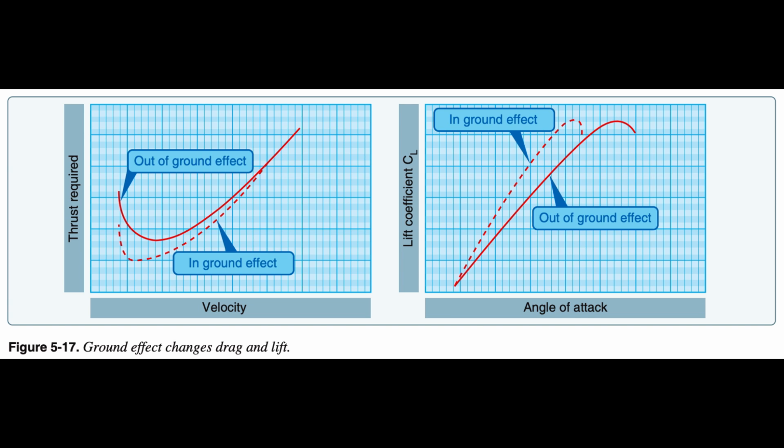During the takeoff phase of flight, ground effect produces some important relationships. An aircraft leaving ground effect after takeoff encounters just the reverse of an aircraft entering ground effect during landing. The aircraft leaving ground effect will: 1. Require an increase in AOA to maintain the same CL. 2. Experience an increase in induced drag and thrust required. 3. Experience a decrease in stability and a nose-up change in moment. 4. Experience a reduction in static source pressure and increase in indicated airspeed.